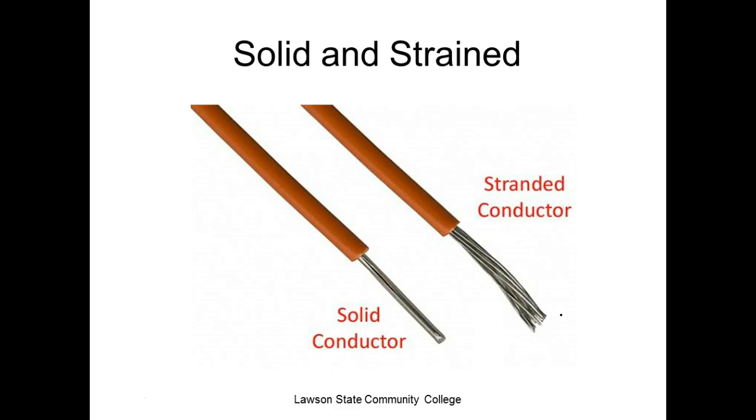Stranded and solid. By the way, you have to be real careful with solid, because if you nick it at all when you strip it, it's going to break really easy. With stranded, if you nick one of your strands, you might be okay. There's a chart that tells you the number of strands you're allowed to nick on a stranded conductor. But basically, the only advantage of a stranded conductor is what? Flexibility. And sometimes that's what you need.